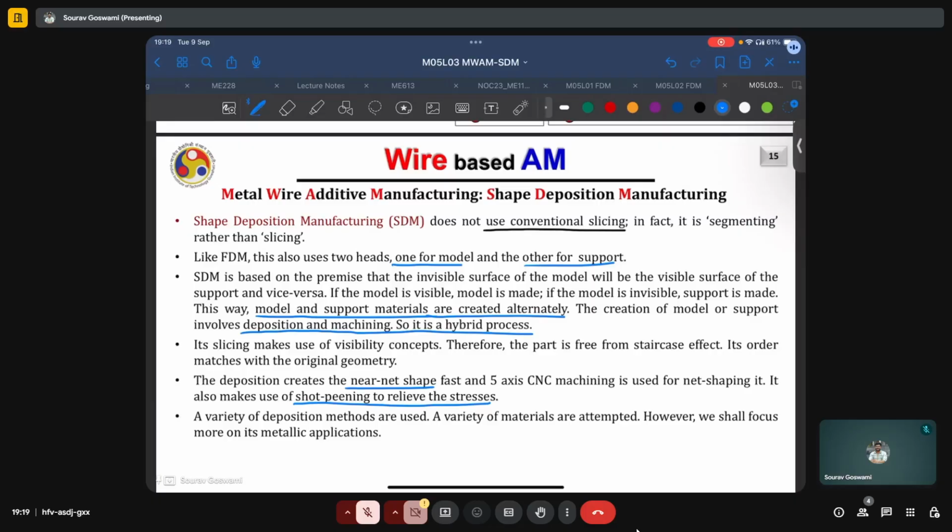Tensile residual stresses can be deteriorating and dangerous because we know that no microstructure is perfect. Part will have some internal cracks, and tensile residual stresses will only serve to enhance the crack propagation and growth of cracks. Whereas compressive residual stresses will help to close these cracks.